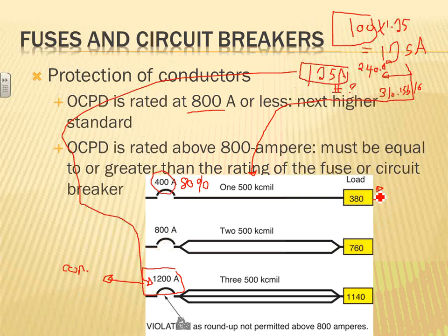Absolutely. Right. And if you looked at it as a load, you would look at that as the actual conductor capacity. Yeah. A number 500 is rated at 380 amps. 500, it's got a 75-degree rated capacity of 380 amps, so I don't think it's going to break. Yep. I don't look at it as a load, I look at it as the wire size. Yeah. But if you, I hate to keep drilling on that one.